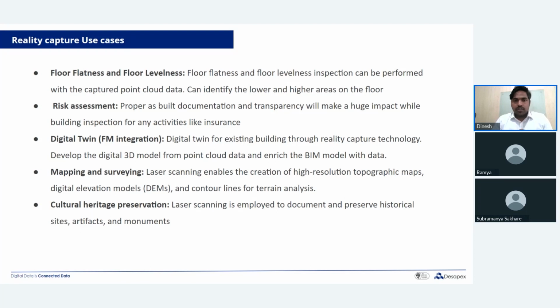So that's where we can scan the entire space and generate the floor flatness reports, and then we basically give the contour, and the higher levels and the lower levels, so defining the slope. So these are the reports that will help us to identify the lower and higher areas, or the elevations, or the slope directions of the present area.